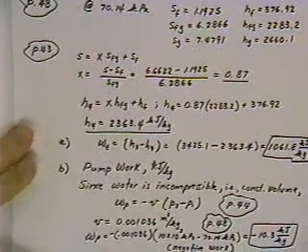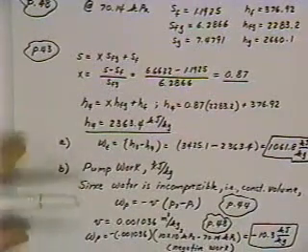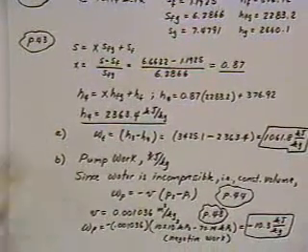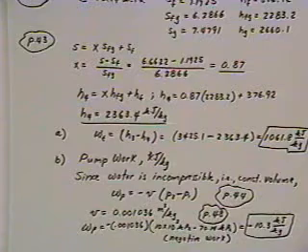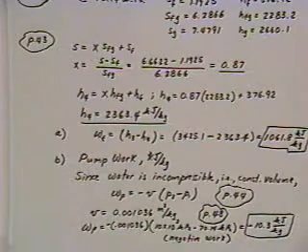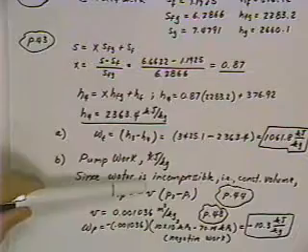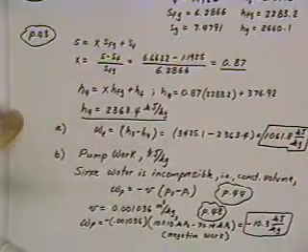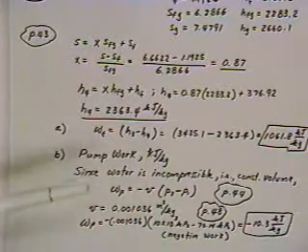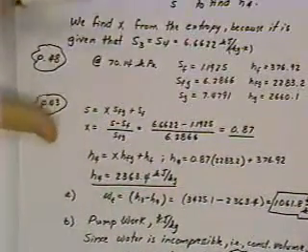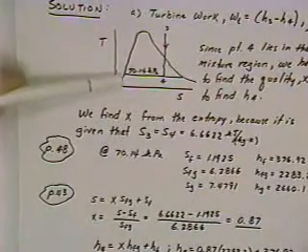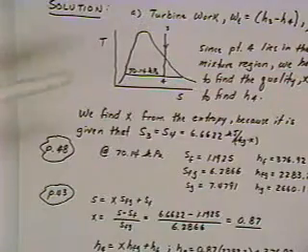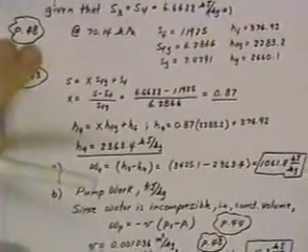We'll make the assumption here that water is incompressible, and so therefore the volume remains constant for water as it's being pumped, and so the expression for pump work is minus V times P2 minus P1. This is on page 44 in the reference manual. And so what we're after, if we go back up to our condition here, entering the pump, and we're pumping from point 1 to point 2 from our original diagram.